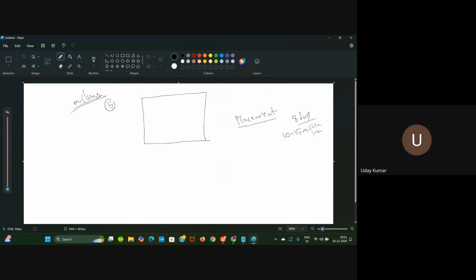This is the placement. CTS can take 6 days. Route can take 10 days. To go for a flow flush from placement to route, it will easily take 20 days and consume more than 60% of 1 month, if you go for a flat PNR of 10 to 15 million instances. What is this flat PNR of 10 to 15 million instances? It is nothing but the netlist containing 10 to 50 million gates.